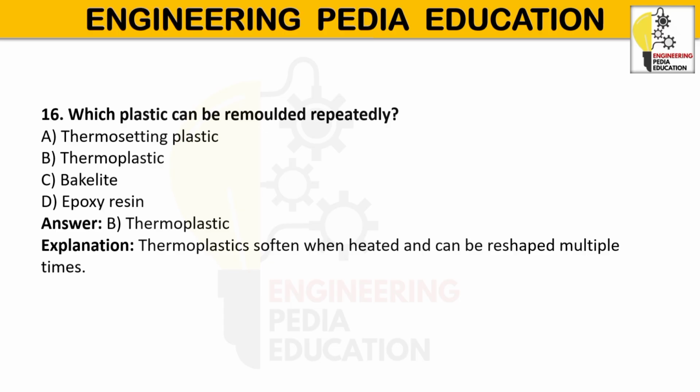In civil construction, thermoplastics are used for water supply pipes, drainage pipes, electrical conduits, insulation, storage tanks, flooring material, and window frames. They are also used in packaging, household products, and automobile components. To conclude: thermoplastics are versatile engineering materials because they are easy to manufacture, reuse, and resist corrosion. Their combination of low weight and durability makes them valuable in modern construction and industrial applications.